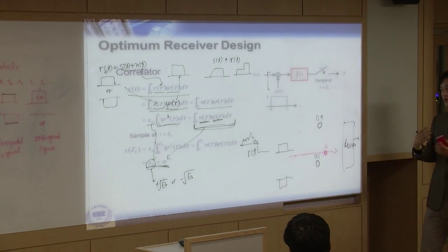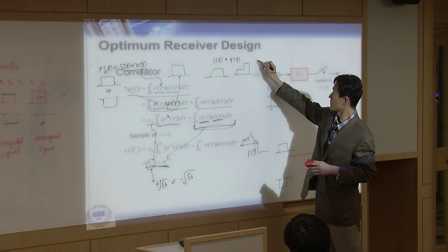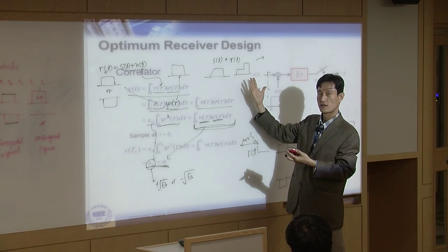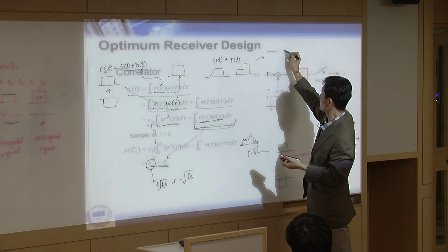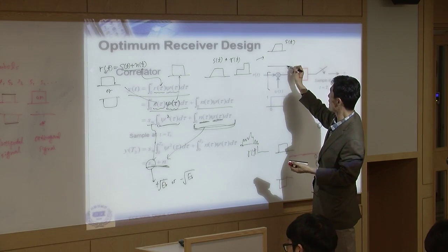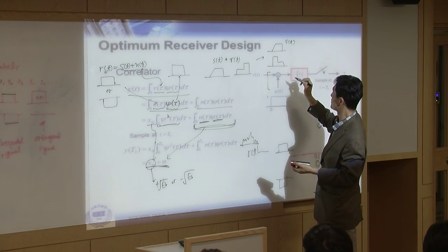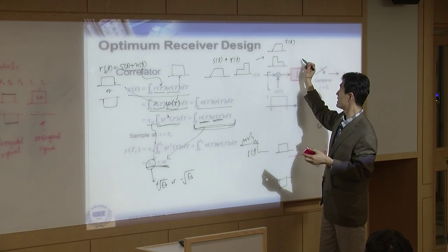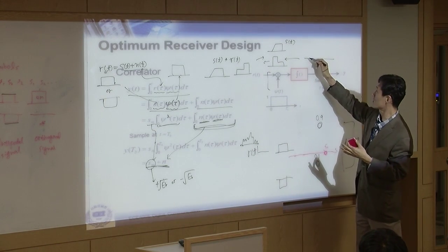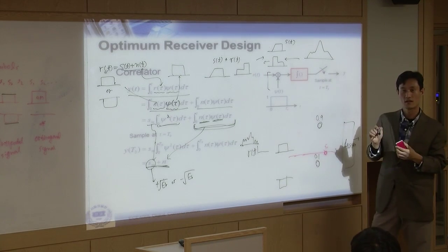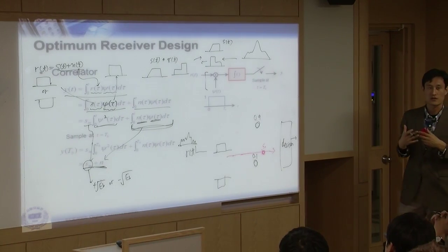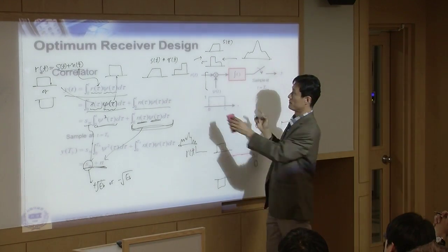When you do convolution, first of all, you flip one of them. s(t) stays like that, and r(t) you flip. And then slide, and calculate some correlation like that. That's going to be convolution.